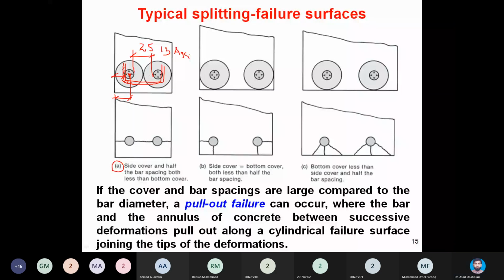So what then will happen when you apply more force and at the maximum stressed section the bar approaches yielding? As a result, the tangential component will cause more and more internal pressure, and those pressure circles may merge because of the insufficient gap, and those pressure circles may touch the edge of the beam. The instant your hoop stresses exceed the tensile strength of concrete, a splitting crack will develop, and along the beam length you may find that there is a crack running at the level of the steel bar.